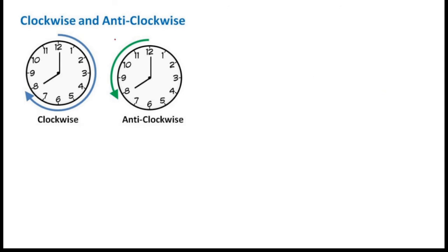Before we draw the shear force and bending moment diagram, we have to state our sign convention. My sign convention is I will consider clockwise positive, and I will not consider the anti-clockwise direction. That means if I draw a part of a beam, and suppose this is a support, I will mark the force like this.